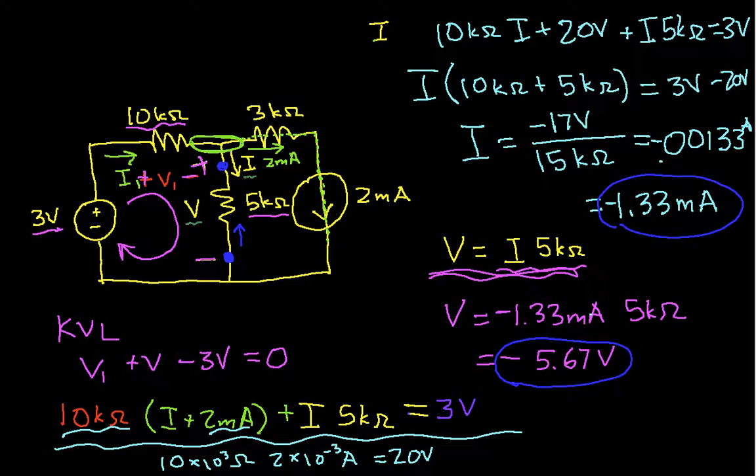So this is the beauty of being able to do circuit analysis mathematically. If you draw pictures where you label the voltage and currents incorrectly, in the sense that you put a plus and a minus in such a way that the actual potential drop across the resistor is the opposite of that, or you draw a current so that the current's actually flowing in the opposite direction, the circuit analysis will tell you by just giving you a negative value for your result.